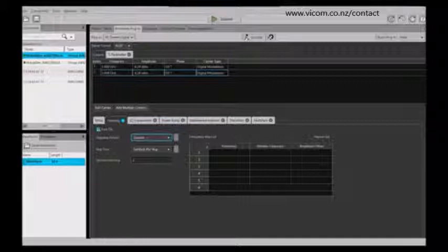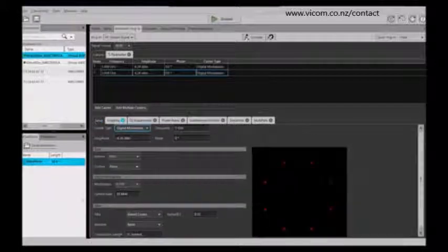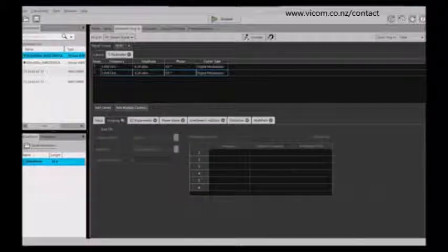As you can see, when I turned on this hopping feature, it gave me an indication that hopping is being used. So when you're in the setup, you know that you're using hopping here. Maybe you don't want to use hopping, but at least it gives you an indication that you have turned that on. So you can go in and turn it off, and you notice that indication goes away. So for any of these tabs, if you do decide to use any of these special features, then you'll know that when you compile that you have those turned on, and then you can easily go in and turn them off if you don't want them. You can change your setup